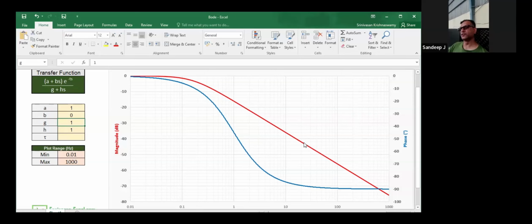When you say feedback, there is a very clear notion of having a substantial feedback in a system. Consider an amplifier with an extremely high open loop gain, and you start to put a lot of feedback, and it starts to sound very constrained. That is like putting in a number of transistors and making the circuit too complicated with a lot of open loop gain, and then you're putting in your feedback, and you start getting extremely low output impedance and high damping factor, reducing distortion, everything. But here the problem is not about that. I agree with what you're telling. Feedback is a problem.